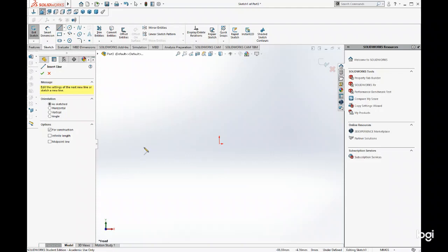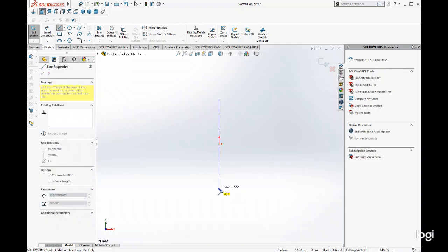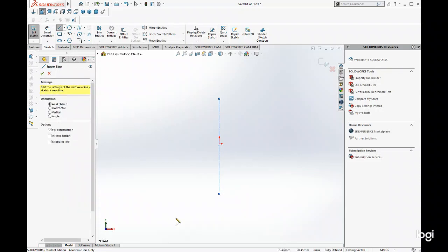and you'll notice the dots are not completely connected. The line is not connected, it's segmented. And I'm just going to start somewhere up here and making sure I keep this vertical. I'm going to draw a line. Now you'll notice this line is still blue. And so I like to go ahead and get these fully defined, and even though it shows fully defined here, it's not showing blue here.